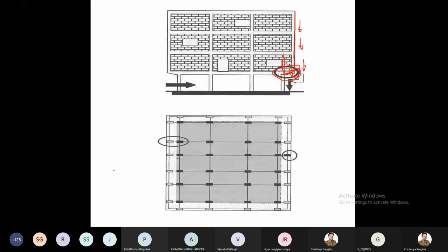So the vertical load coming from the column becomes a shear force in this particular beam, and this beam carries large shear. We know shear failures are brittle failures, and therefore we have observed damage to these balconies during earthquakes, right? Now you see, this is a very awkward load path, a very awkward load path.